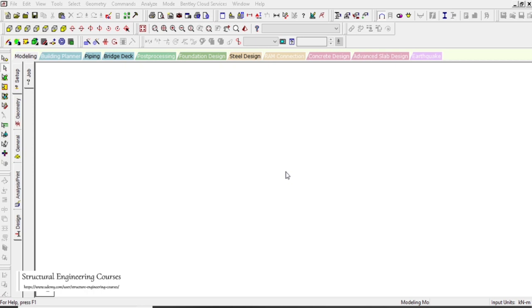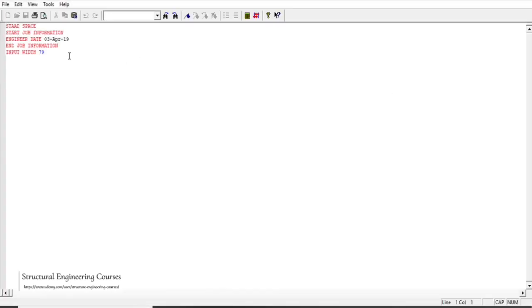And in this lecture, we will try to model a truss tower, and then we can check how STAAD calculates the wind load on a particular structure automatically. So first of all, we need to model a truss tower. So we go to the editor file here, and then we enter the units, left click on joint coordinates, enter the joint coordinates as 1, 0, 0 and 0.